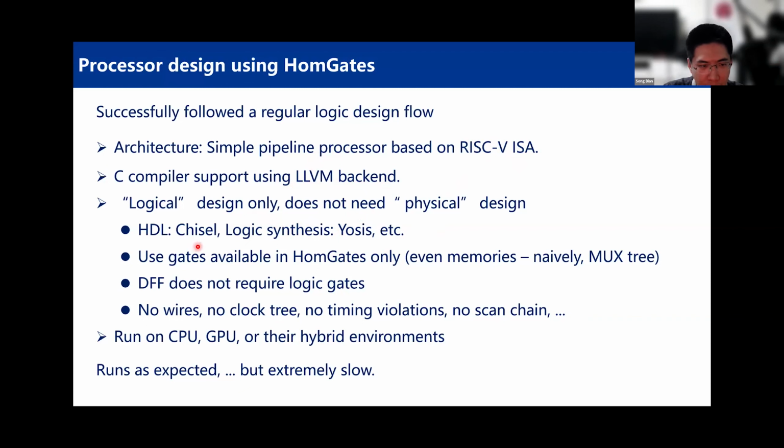And we use Chisel to design the overall processor. And for the gates, we use the given gates in the earlier version of the TFHE library, where we have ANDs, NANDs, and 2-input, 3-input ANDs, except we have redesigned the memory, because the memory is a very strange unit for FHE to handle.